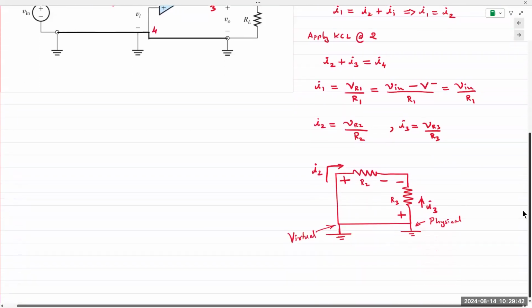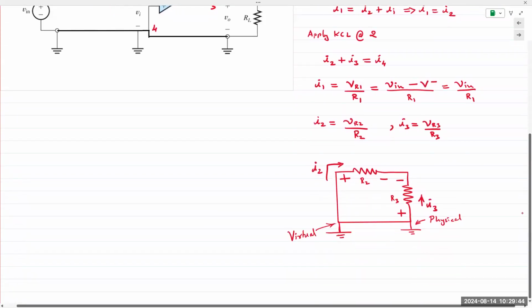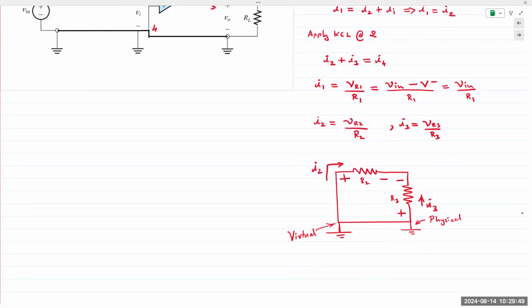And again, I would remind everyone that nonlinear, active elements like an op-amp, transistors, and diodes have many different kinds of equivalent models. So you would try analysis with one kind of model, look at the solution, and see if the solution makes sense within our system. If it doesn't, then that model is not valid for that circuit in those boundary conditions. We try a different model, and if it works, then we say, yes, this model is valid. Same circuit, but it depends on how you're looking at it.